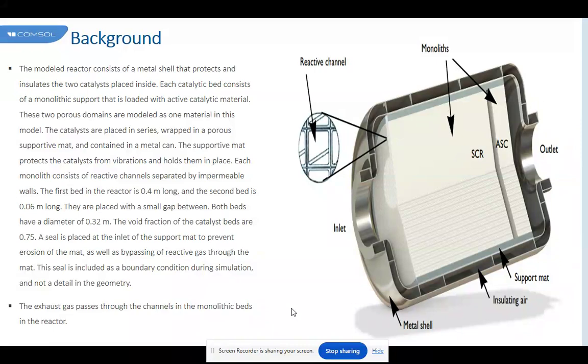The main results in this work are summarized here. The first one is a mathematical model. We consider a one-dimensional two-phase mathematical model of a straight channel washcoat catalytic monolith with the following assumptions. Conduction and diffusion in the axial direction is negligible in the fluid phase. The fluid flow in the channel is laminar, either fully developed or developing. The pressure drop in the channel is small so that its effect on the concentration and velocity may be neglected.